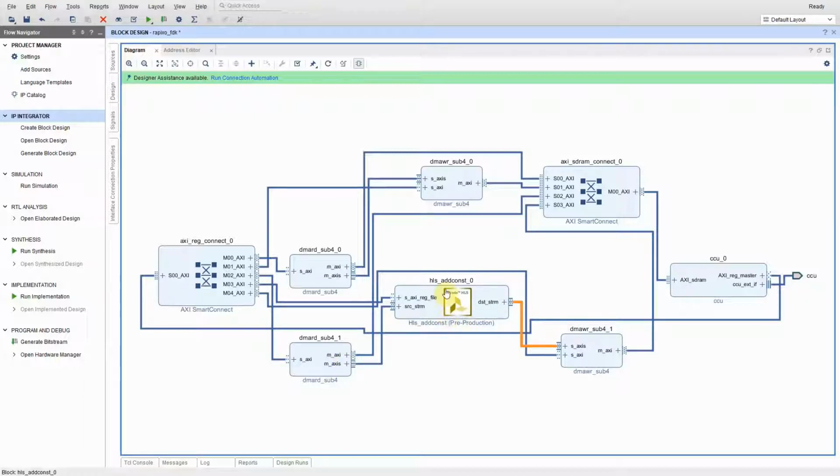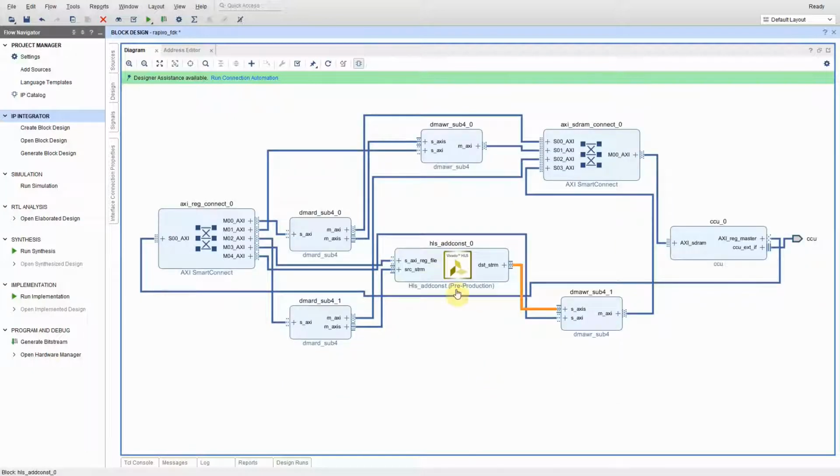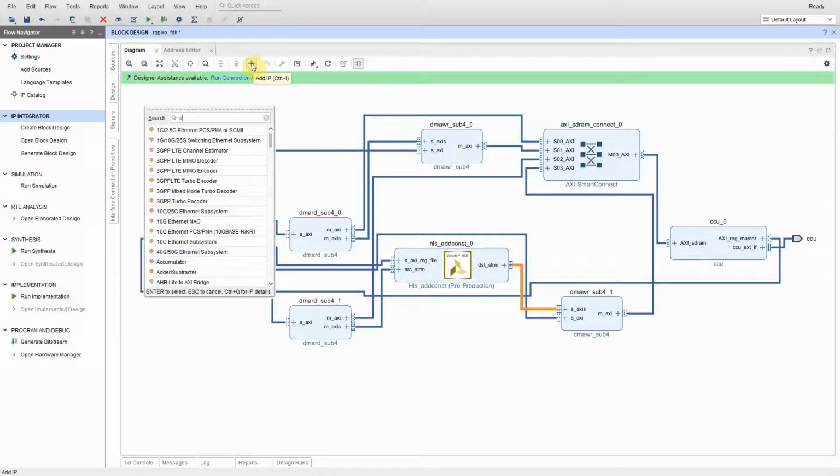If we add the remaining PUs in this way, the final design will have a lot of transfer units and take up a lot of space in the FPGA. In this case, we only want to test the examples one at a time, so a better design would allow sharing of the transfer units. Sharing transfer units, or TUs, requires software-controlled routing of data streams. So we'll add an AXI4 stream interconnect IP, which is basically a stream switch.